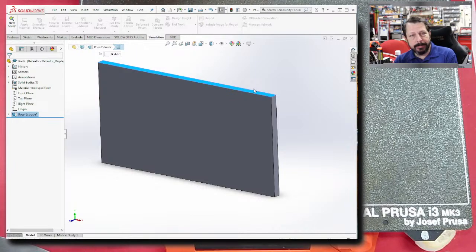Is it going to be demolded? If it's going to be an injection mold type part or a cast part, it's got to have a way to demold, and you can tell it which, if that's true. In additive fabrication, that's not necessarily an important thing. You're not molding, and you can pretty much fabricate in any direction.